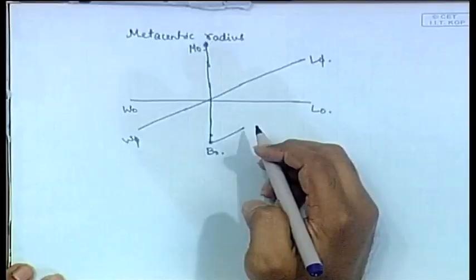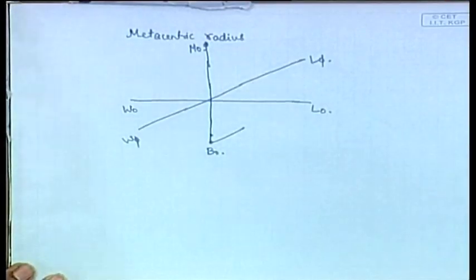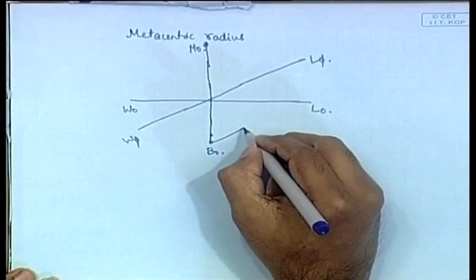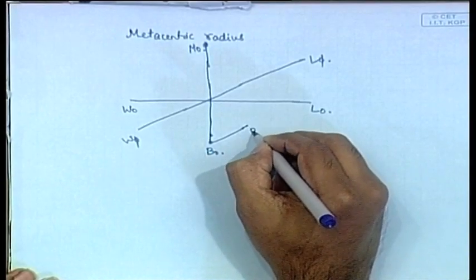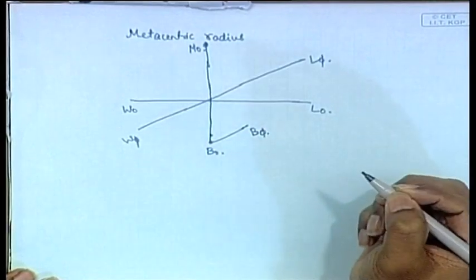They keep asking how the center of buoyancy shifts. The only thing you have to know is what the center of buoyancy is. It means the centroid of the immersed volume, that means whatever volume is inside. Now, if I keep increasing the amount of volume on the right side, obviously the center of buoyancy will shift to the right side, and the other side likewise. That is the center of buoyancy. Now, B0 to B1. Obviously it is tilted there and it has gone from B0 to B1.